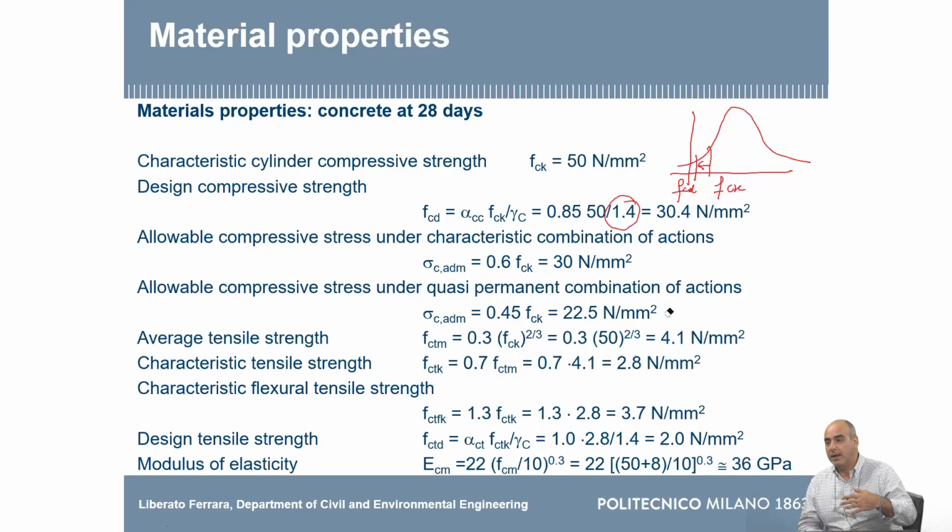But which are the loads which produce creep? Because as we said, creep is a phenomenon that requires some level of stress to stay permanently there. So surely the dead loads, the self-weight of the beam, of the element, produce creep, because if the element exists, it has a weight. We live in the gravity field of the planet Earth, so we cannot avoid that.